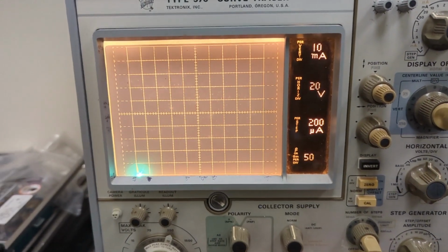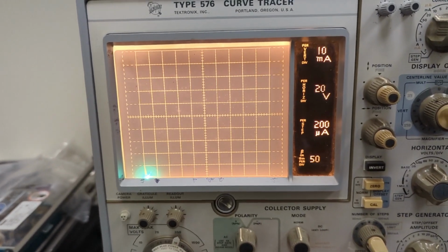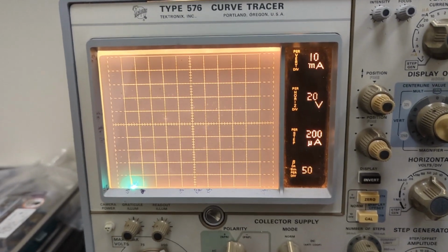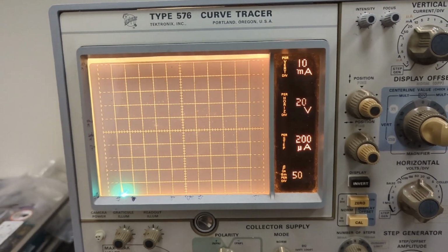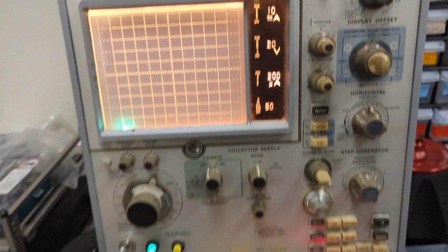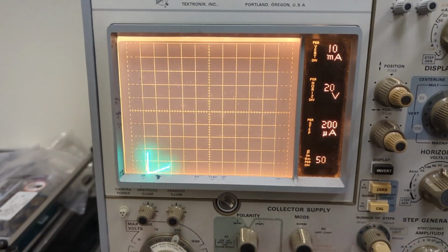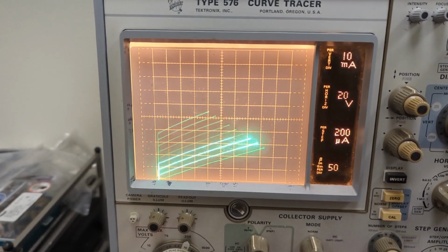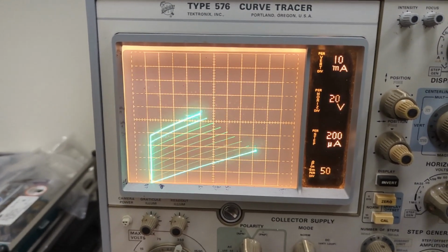Now, when I did remove it, I was able to get that forward bias voltage drop of roughly 0.5 volts. But check out the curves for both of them. They're very different. This one on the left, well, actually I forget which is which, but I'll know once I apply a collector. Oh yeah, check this out. This is the negative 100 volt